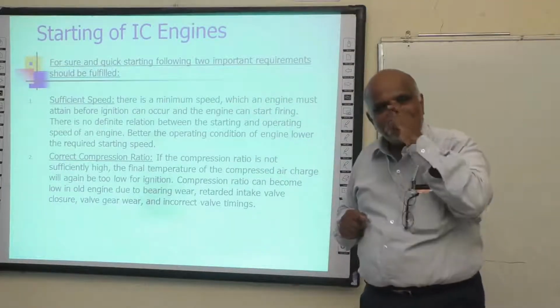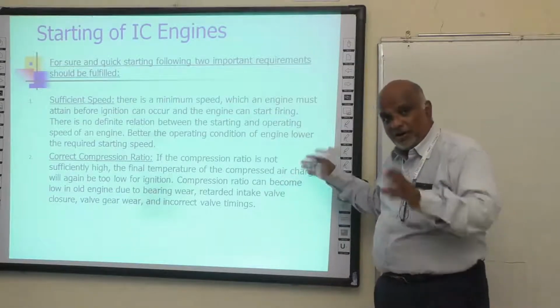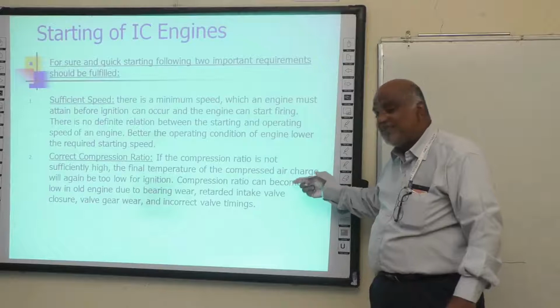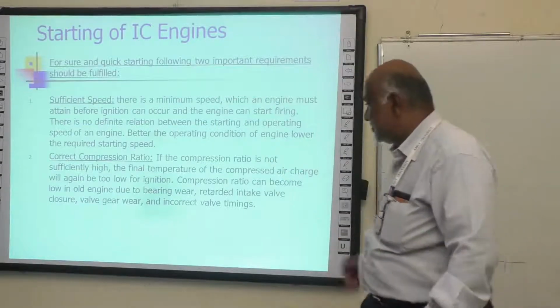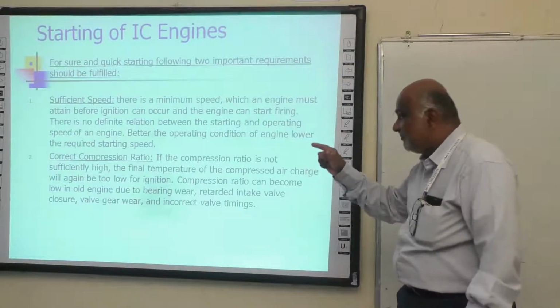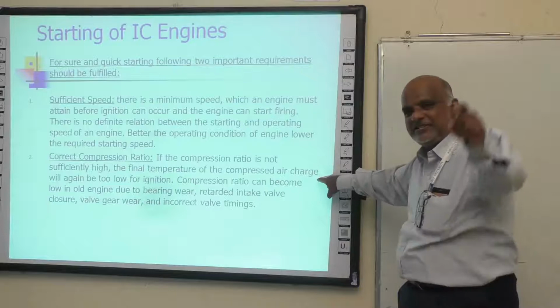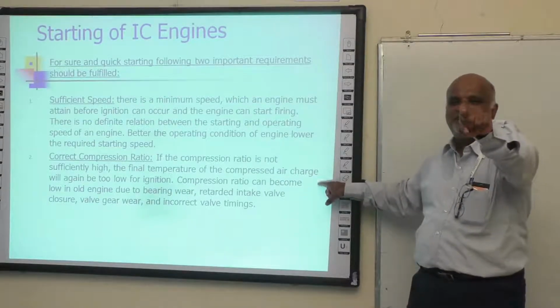Next. The second point is, for a good starting system, you should have a correct compression ratio. What is this compression ratio? If the compression ratio is not sufficiently high, the final temperature of the compressed air charge will be too low for ignition. I am talking about the final temperature of the compressed air.